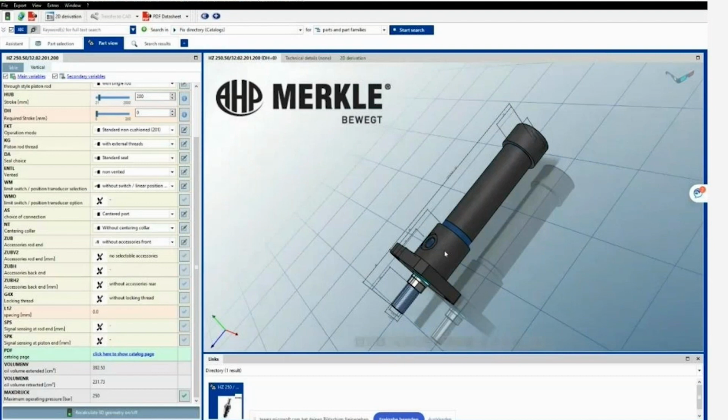Die casting is a very dirty environment. They have a lot of metal chips always on the tools because of the aluminum. And for this, you need to have hardened steel and stronger steel, let's say. So we don't make a difference between where it's going. All our cylinders have hardened pistons, and this is a very big advantage when it's being used in die casting.